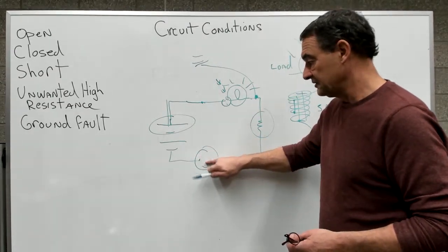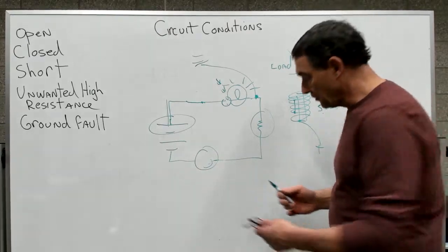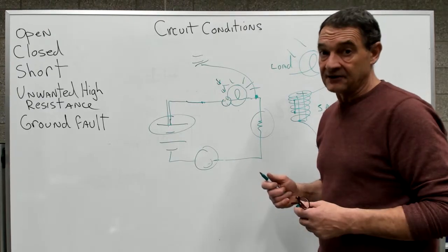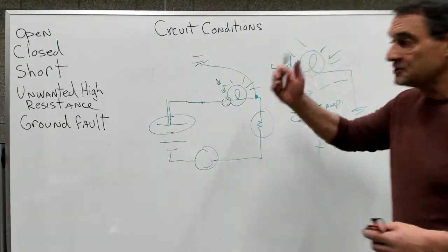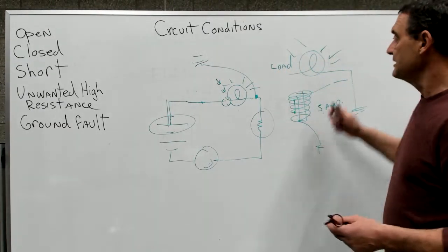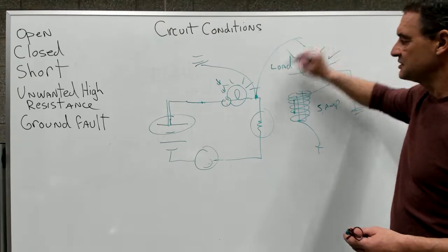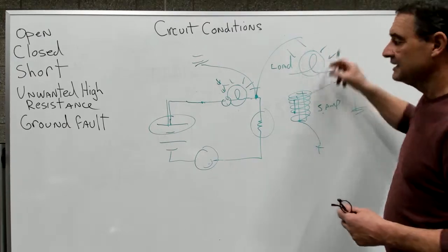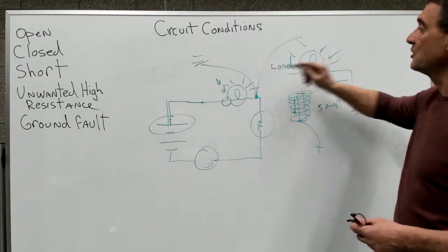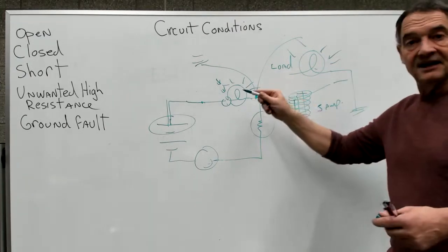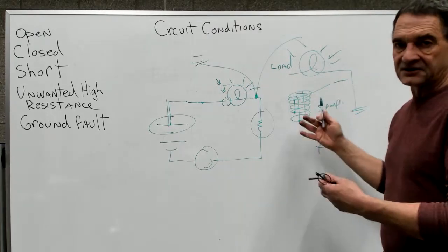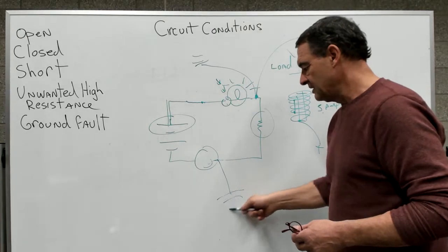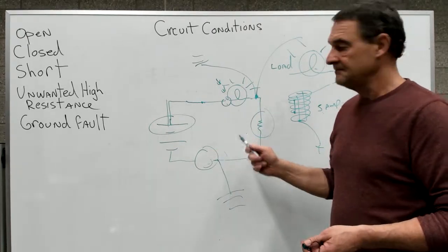That is a ground fault. And traditionally, if you throw another fuse in there, you would find that it blows out right away, and you would understand we have a ground fault. Often short circuits are confused with ground faults, because if the short that's supplying this load is large enough, it can blow the fuse as well. But you will find lights go on here. Typically on a short, you will have this light come on and that light come on. Somewhere else, the power is coming in. A ground fault, always, when it goes to ground, blows the circuit. So that's a ground fault.